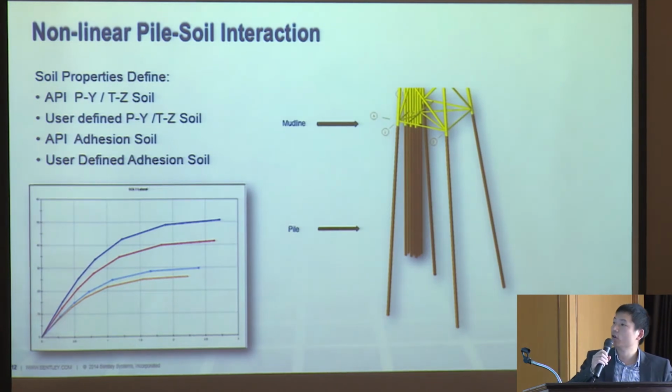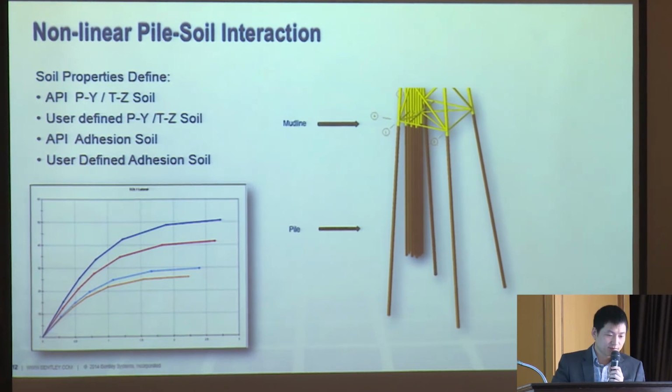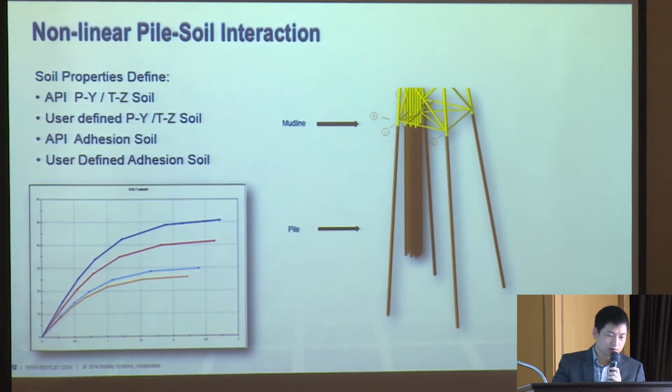And for a fixed platform, you need to consider the nonlinear pile-soil interaction. And SACS supports different formats of input soil data. First, we support the standard user-defined PY, TZ, QZ soil data.